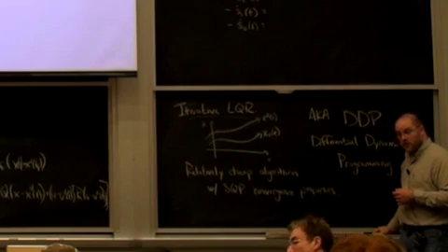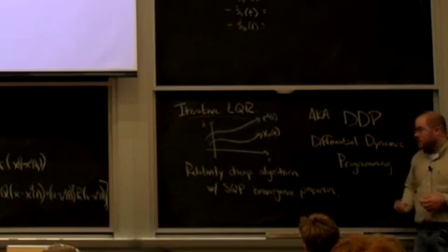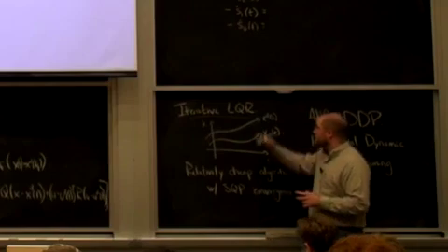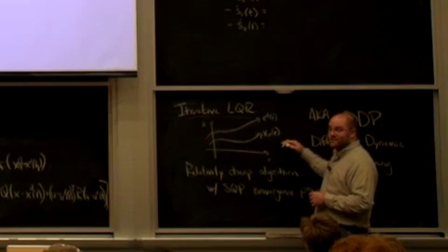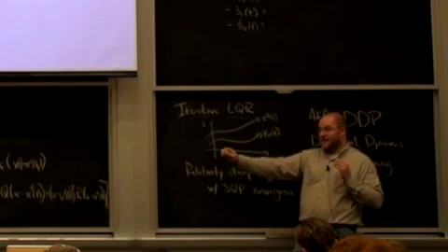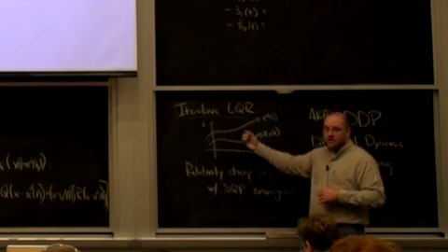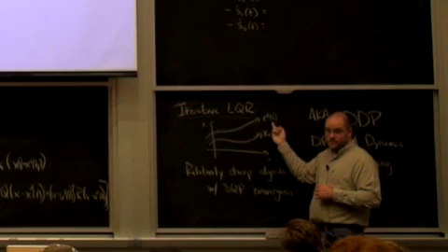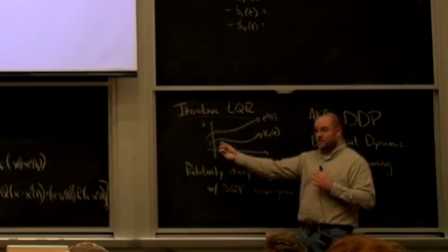So this X naught trajectory isn't a trajectory that you found by doing RTRL or something like that? This is something different? So good. This could be a stand-in replacement to RTRL. I could start with a random X naught trajectory. Maybe it's better to start with a random U trajectory, simulate it, and get an X naught trajectory. Then it will quickly reshape until it gets as close as possible to this X desired trajectory. You're reshaping your control actions that will get you to the X desired. Yes, I'm reshaping U, resimulating to get the new X.